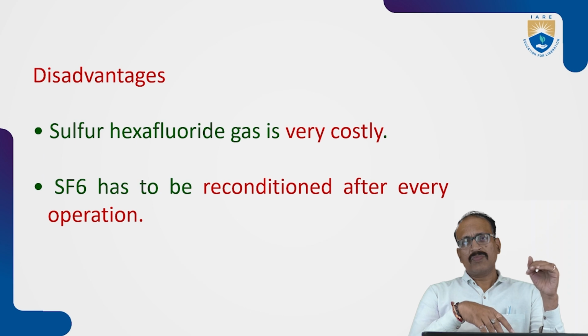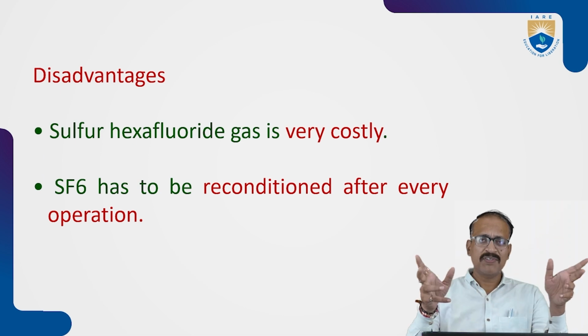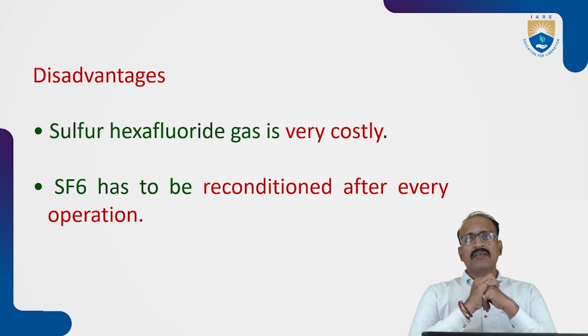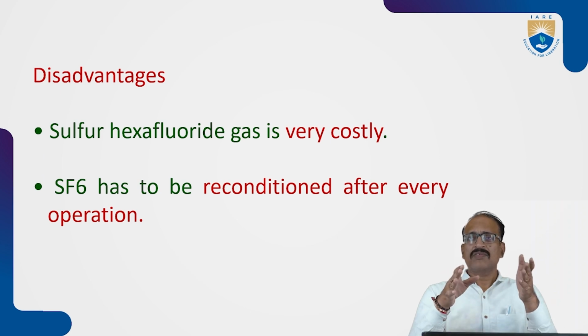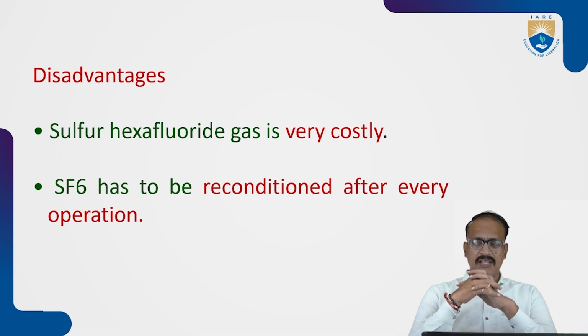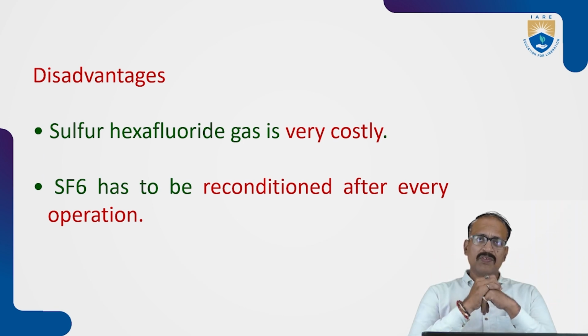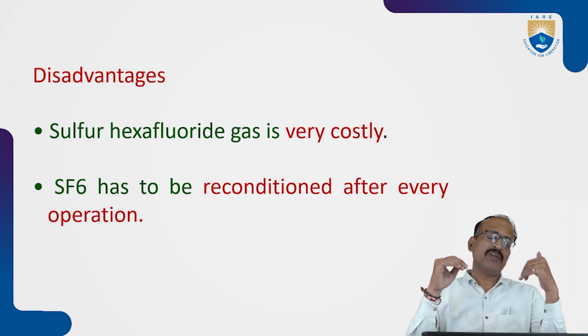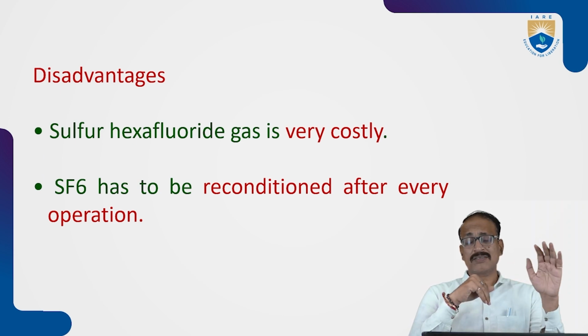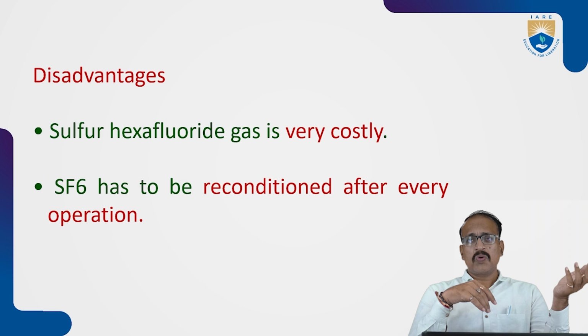So in the oil, the hydrogen will create turbulence, and it will disturb this matter, which is the cause for this restriking. In the case of SF6, it is able to absorb the electrons, and also its dielectric strength is very, very high. So the chance of restriking will be very, very less.